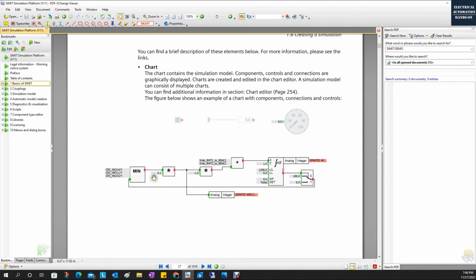As we can see here, this is the multiply. This is an interface that allows this analog signal to transfer to the PLC. And more importantly, some high-end calculation function blocks we can use from this software library. For example, this is the integral. Integral is a very commonly used function block in this software. For example, when we simulate a water level going up and going down, when we feed water into a tank, the tank level going up and down basically comes from this integral function block.